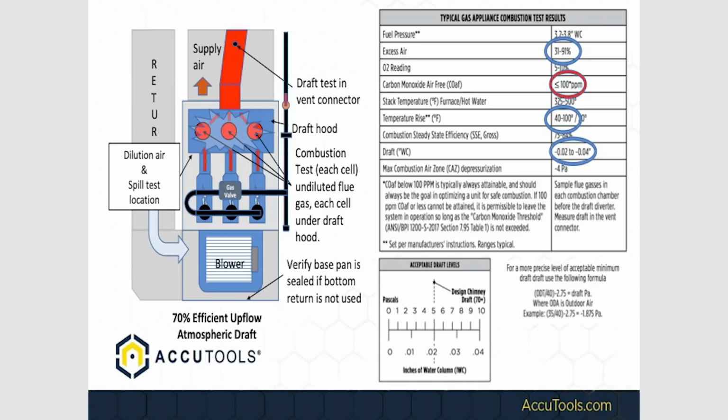So here I've got a draft hood. That draft hood loses 10% of my efficiency of my appliance because it's constantly sucking air out of my home, whether I'm burning it or not. Standing pilot loses 10%. Uninsulated cabinet losses. So yeah, I got 81% combustion efficiency, minus the draft hood, minus the standing pilot, minus the uninsulated cabinet. That's a little bit more representative of the AFUE than appliance.